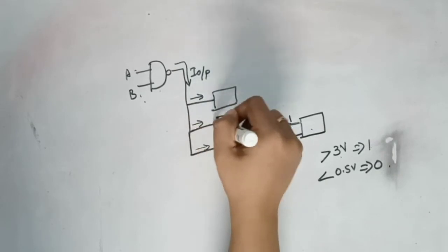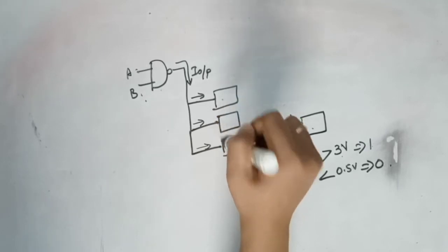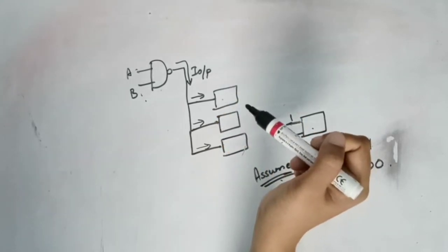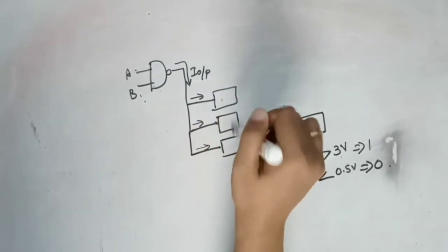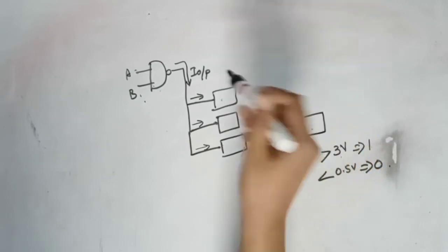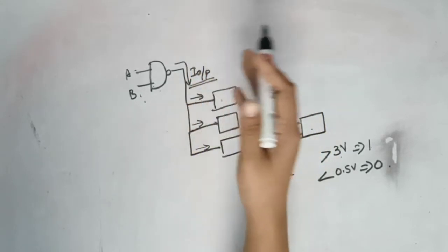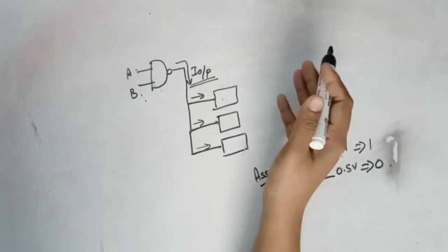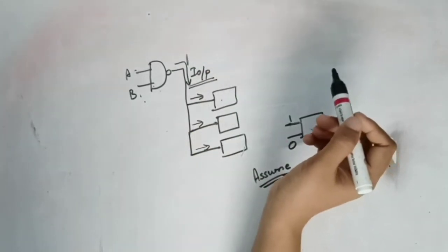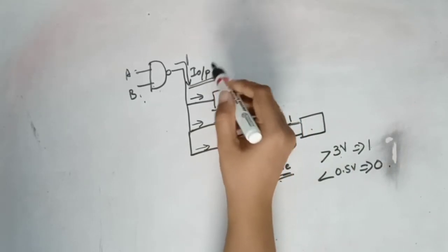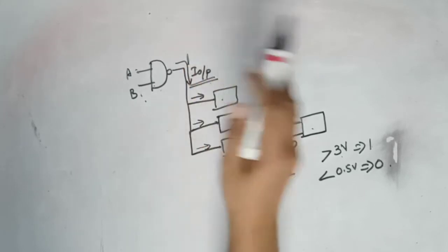These splitting currents are entering the inputs of these gates, because the output of this gate is driving so many gates. So the output may be associated with a 1 or a 0. Suppose you have a logic 1 here. So you have a high current, a particular current here. Logic 1 means this current should be at minimum so much value.